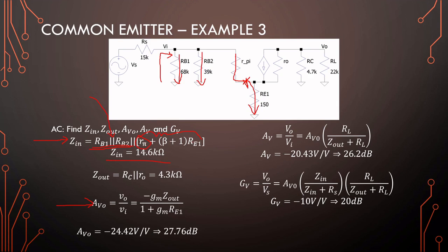So if this is much greater, our input impedance will be independent of R pi. That is a very good thing. Right. So remember that for designs.